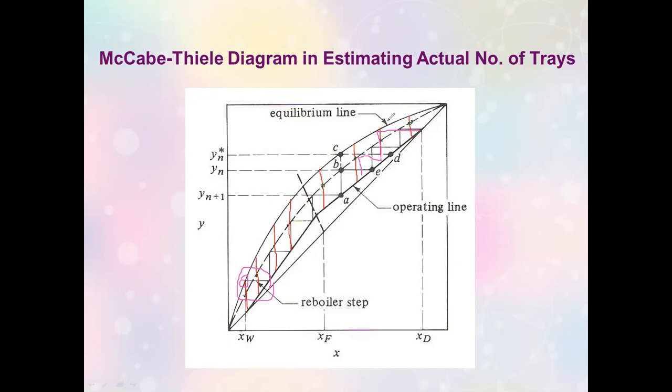There's no problem using Murphree efficiency without the graphical technique, class. It has to be really drawn this way if you are to use the Murphree efficiency in determining the actual number of stages. Because based on the formula, we don't have a formula for Murphree efficiency that is based on the actual number of stages, but rather what we have are concentrations. Okay, this one you can read.